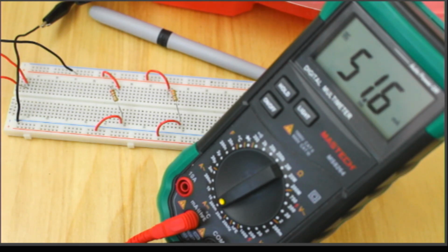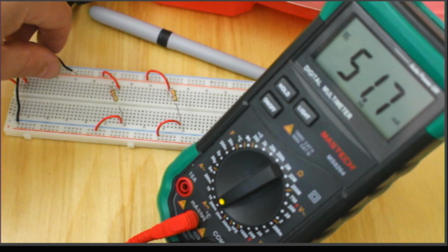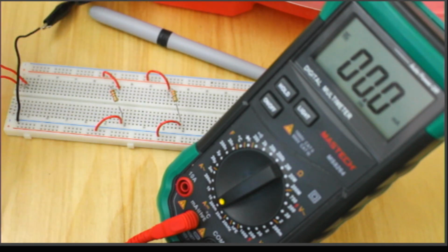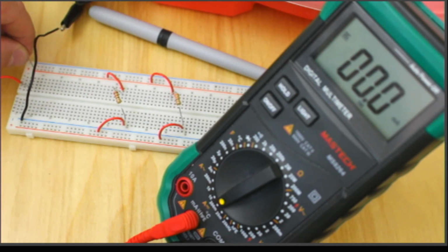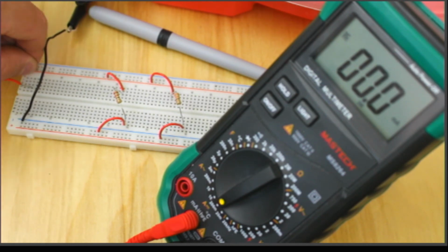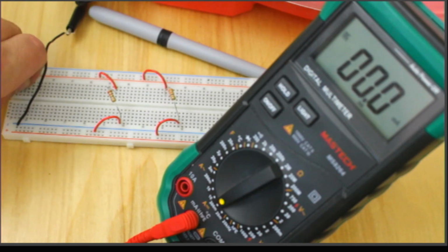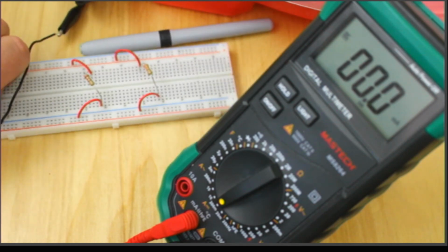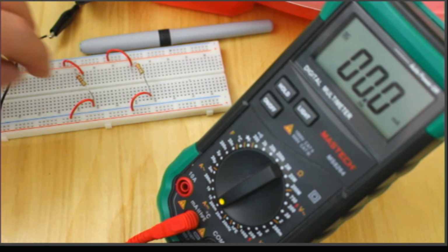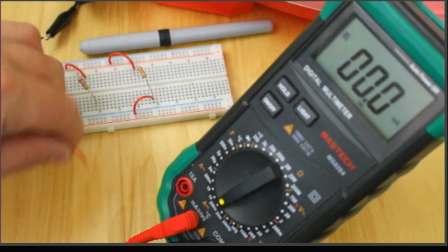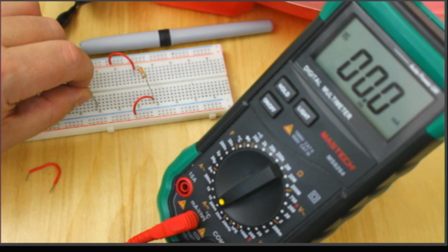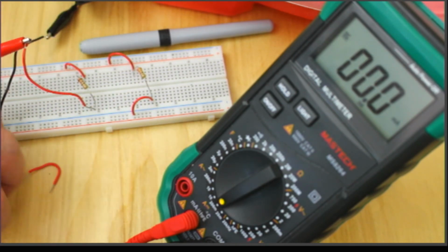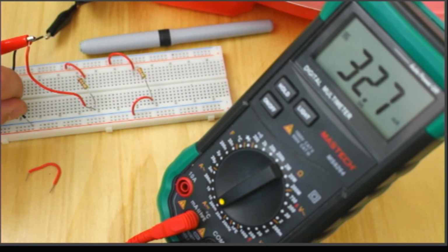Okay. Now, if I wanted to do the individual branches, I'm going to go ahead and unplug this, put my power back where it came from, and now I want to measure an individual branch. Okay. And so probably the easiest way to do that is to just remove, like, the bottom wire there, put your positive lead in where it touches the lead of the resistor, and then put your negative lead into the bottom terminal.